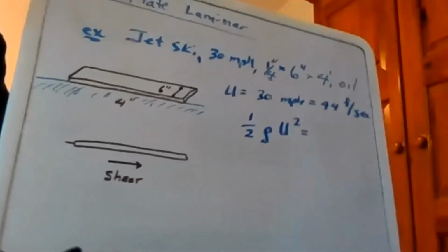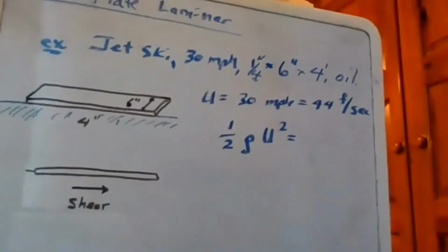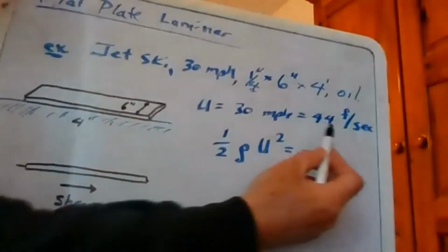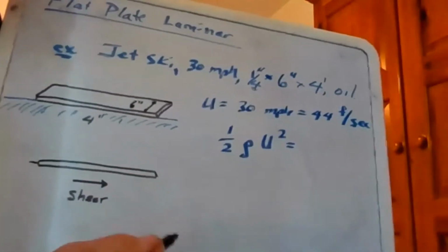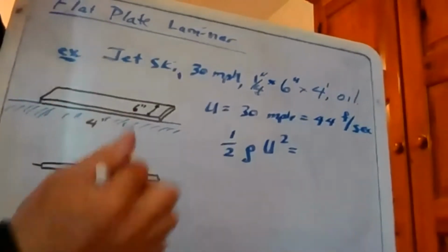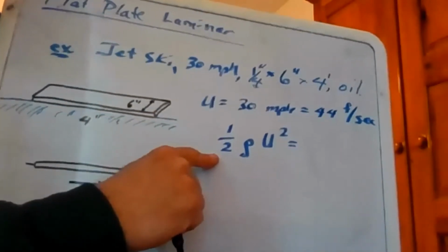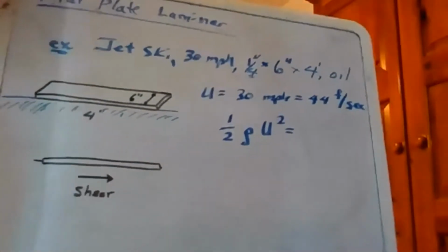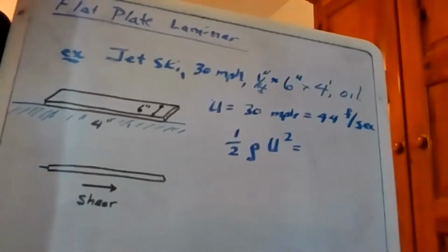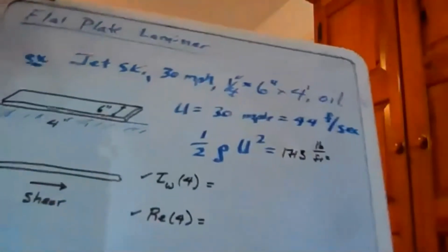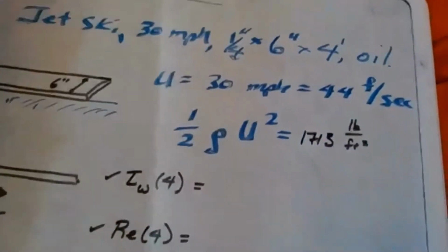All right, getting going on some of the math for background. 30 miles per hour is equivalent to 44 feet per second. We know that probably somewhere in this core calculation, we're going to have to do 1/2 rho u squared. So why don't you get that number up there just for background? Okay, so that basic calculation, with a little bit of practice, becomes second nature.